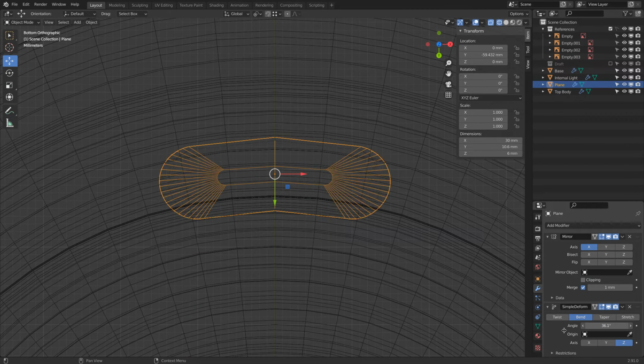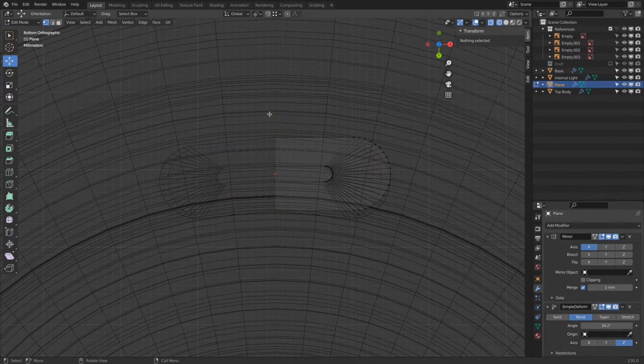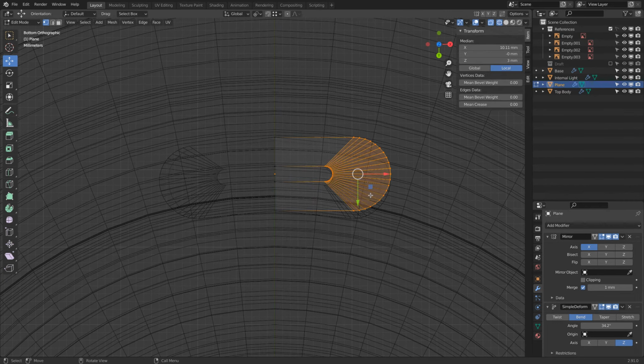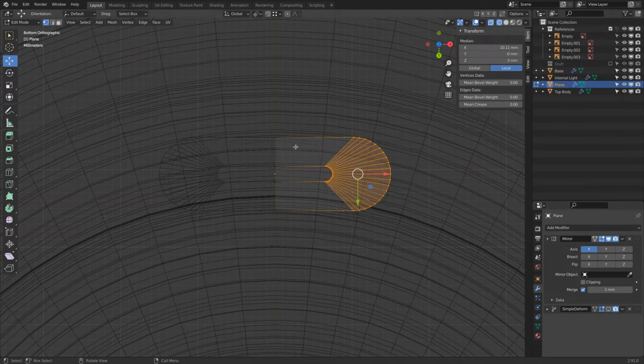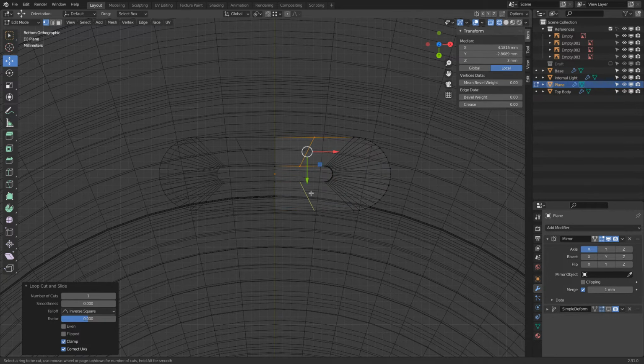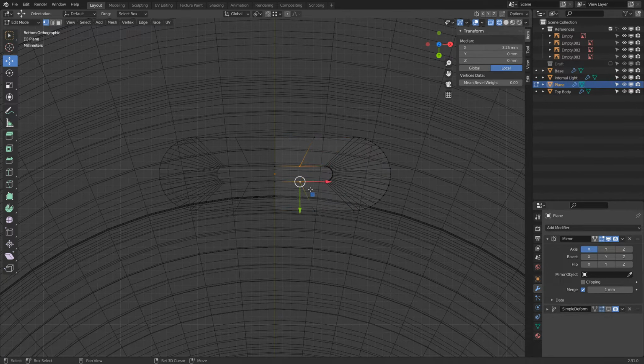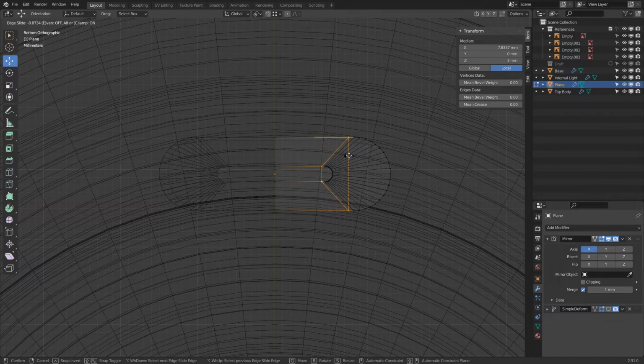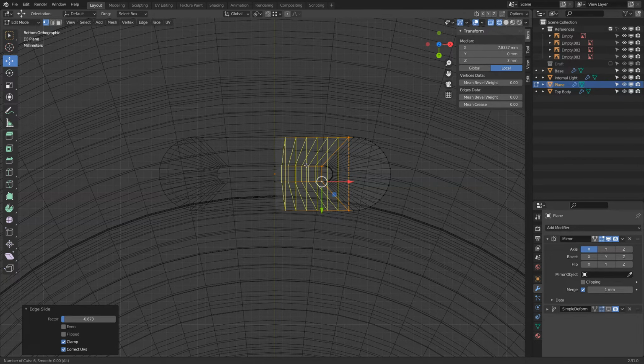Oh, cool. Okay. Yeah, but what's happening here? Well, we have this geometry, and then we have this geometry, and then all that moves, but we have nothing there in between. So let's add this. What's missing? Let's turn this off for the moment. Control R, Control R. Also here again, I will select these points and J, do the same here and J. Now I have a loop cut, which I can G G, slide over there, and then Control R, and then move my mouse wheel, and you see I'm adding more subdivisions. Click escape.